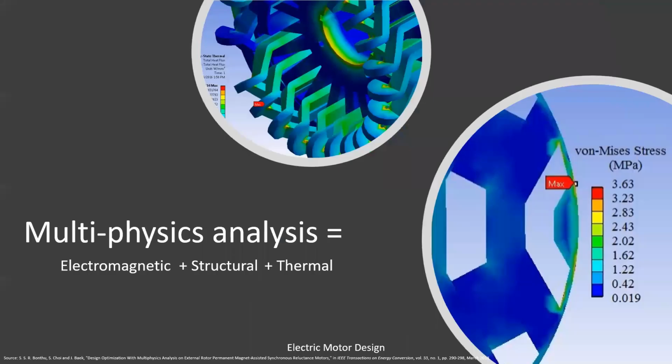If a motor is run continuously, it can go up to 80, 90 C. So it is really important to do thermal analysis on your electric motor design so that once your motor is in production, it doesn't fail because of an over-temperature fault or something like that.